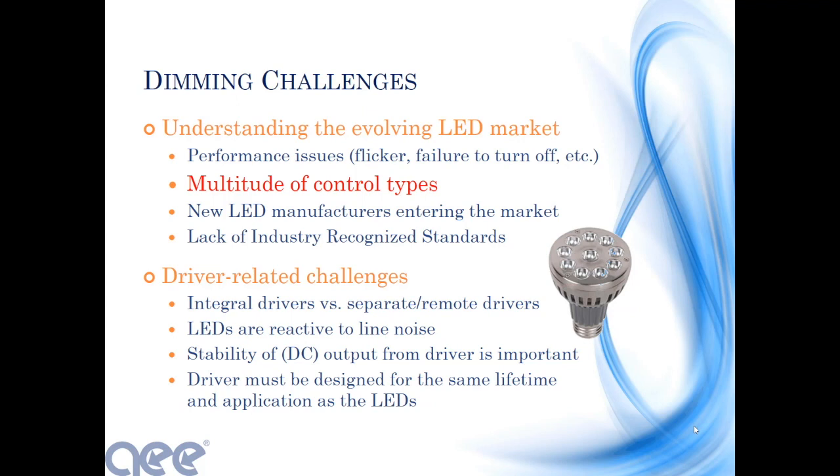LEDs are reactive to line noise, so you do have that issue that can cause some problems. Stability of the DC output from the driver itself is important as to how it's going to affect the LED light engine. And then this is the other key that we touched on at the end. The driver must be designed for the same lifetime as the LED. When they first came out, LEDs, 100,000 hours, great. You know what they're talking about? They were talking about the light engine. They weren't talking about the driver. You've got to read the little fine print and the asterisk at the bottom.